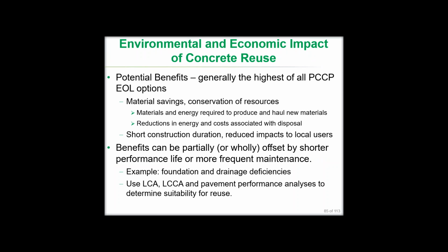So if we look at the overall environmental and economic impact of concrete pavement reuse, as with asphalt pavement reuse in general, I think that the potential benefits are usually the highest of all of the end-of-life options, because we're not expending a lot of energy, we're not consuming materials that will be required for rebuilding a pavement, and we're not hauling materials.